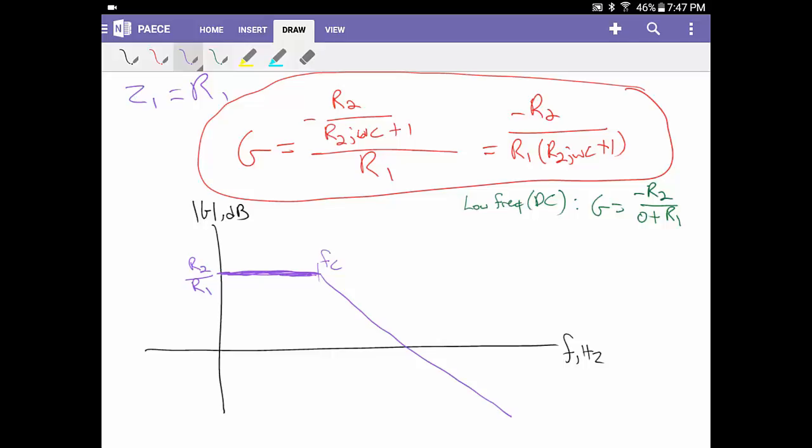So now you've seen a low pass active filter. And in this case, look what happens. We have a much more linear passband, a much more flat passband, which is a lot easier to design around. You don't have to worry about, well, if my signal swings from 10 hertz to 100 hertz, now I have to worry about it being attenuated or have a different gain applied to it.